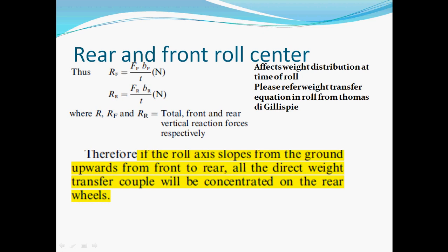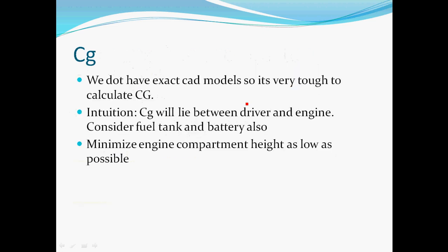So it's a good habit to do. And moreover, as your rear has more weight, your rear roll center can be a bit higher than your front roll center. This is important. And CG is a very problematic thing.